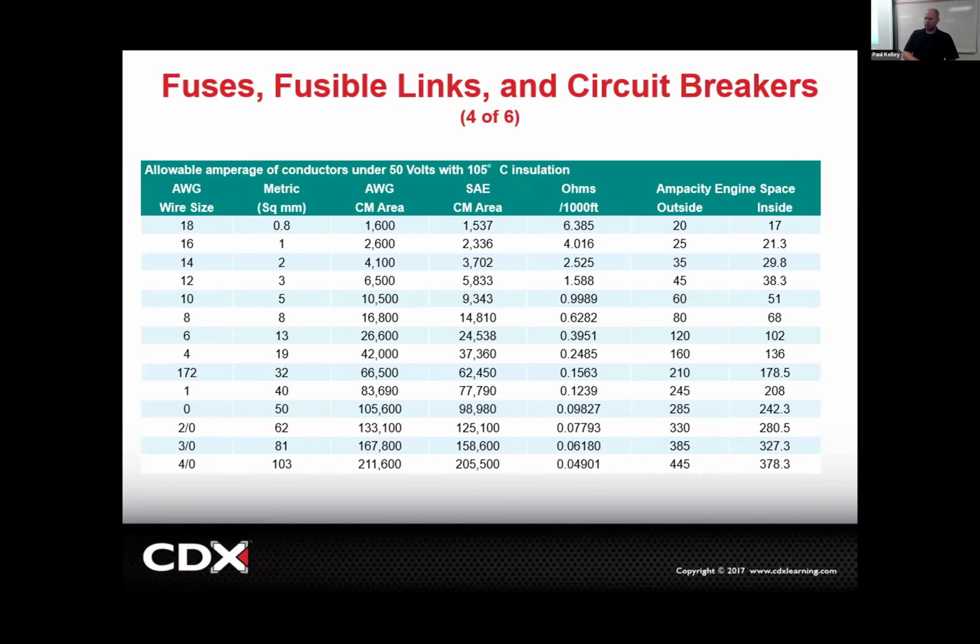Now, if it were me, when I did my construction and built my shop, I thought, well, I only need 30 amps right there, but you know what I'm going to do? Run a wire that'll handle 50 amps. Why? Because I don't know what I'm going to do in the future, and I'm okay with spending the budget on that. Also, a house or a shop doesn't have to move and drive and get gas mileage, right? So for me personally, I ran oversized wire all over the place, because if I want to add to the circuit or run bigger things, I don't want the breaker tripping. But from a manufacturer standpoint, keep in mind, every time you run a wire size bigger than it needs to be,